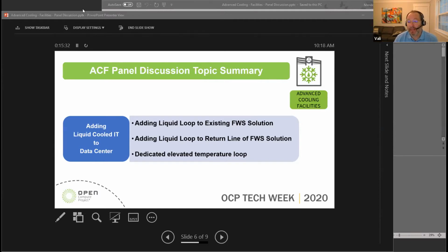If you go too high in temperature, like if you could theoretically deliver 50 C water, facility water around the clock, because there's probably not a climate on the planet that can't produce 50 C water, but it takes a penalty, takes a hit on the IT equipment, because now the IT equipment is going to be operating at a much higher temperature also. So some of the benefit of having liquid cooling is taken away from that standpoint.